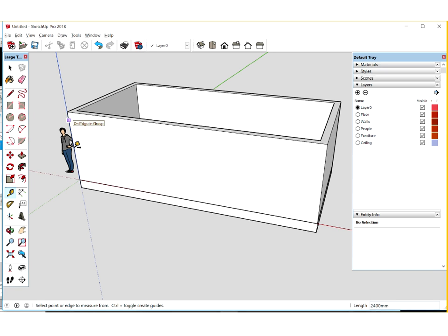If you accidentally click on the midpoint, that's just going to give you an end point. It's going to give you a reference point rather than a guideline. But if you hover somewhere over the straight edge, you can click and release, move in the direction you want, and just type in a dimension. I'm going to do 900 here, and then enter. Now, two options for building a door. So offset a guideline there and put up a green tick once you've done that. You can choose your distances, that's okay.